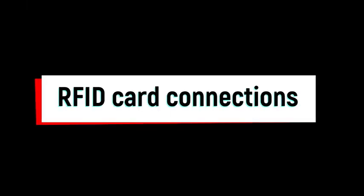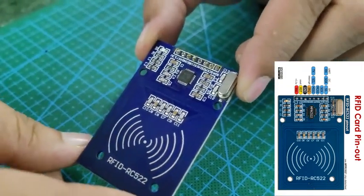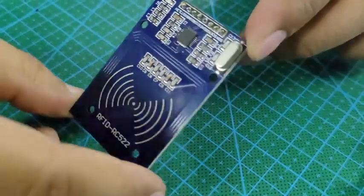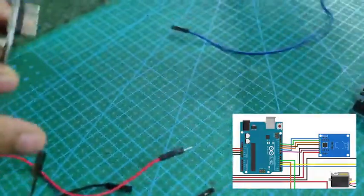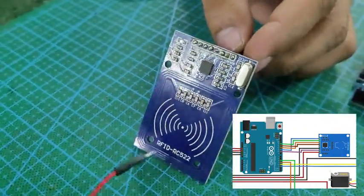Now let's start making the RFID card connections using the jumper cables. This is the RFID card pinout we have seen. On the rightmost side is SDA, SCK, and it goes up to 3.3 volt on the leftmost side. As per the circuit diagram shown in the earlier picture, as well as the picture in the bottom corner of this video, we are connecting all the pins.